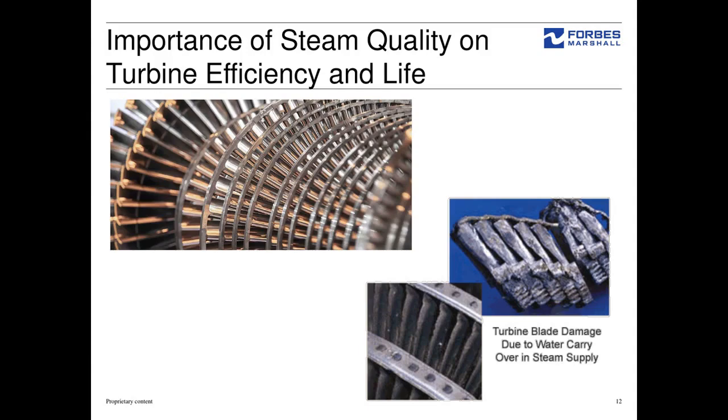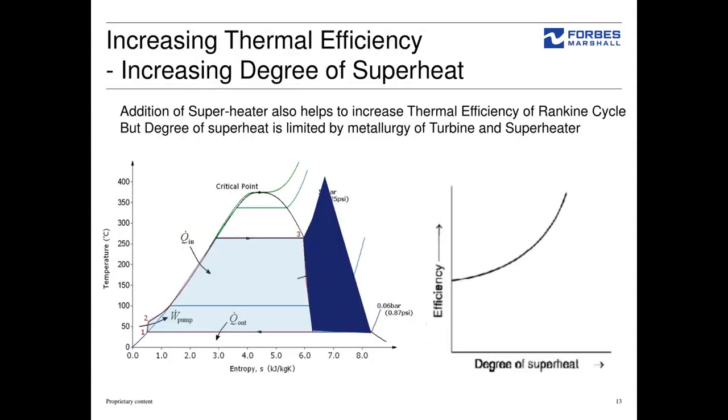and that's why it is always recommended, whenever you are using a steam turbine, that we should have superheated steam at the inlet of the steam turbine. In most cases, particularly in large thermal power stations and also in captive power plants, people use superheated steam turbines, which are quite efficient in operation.